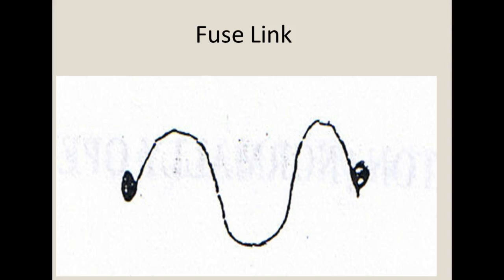And so they used to put it in places where, if they put a fuse, a customer might go in there, know just enough to be dangerous, and put something else in there and try to reuse it again. So we had these fusible links, so you had to know what to do to take that out and repair it, and you knew to go looking for why it tripped in the first place. So a fusible link is something that they want an expert to look at if it blows. Does that make sense? All right.